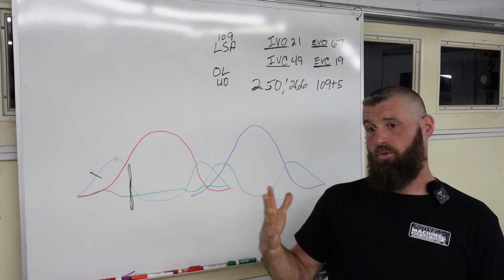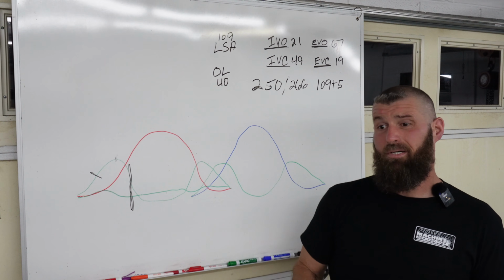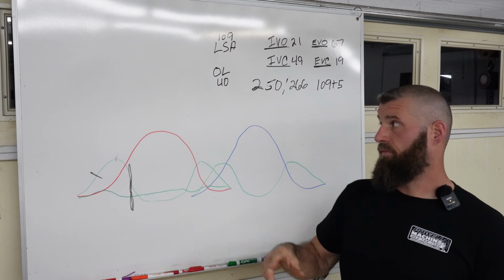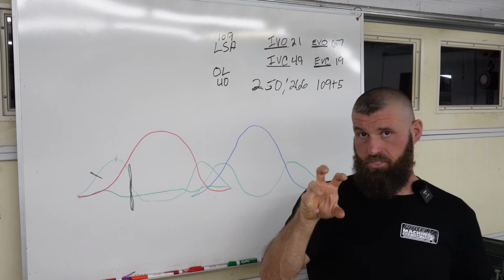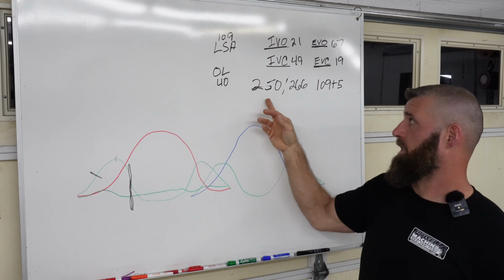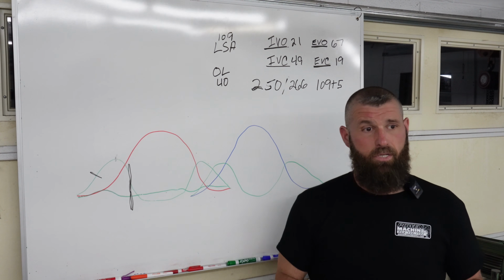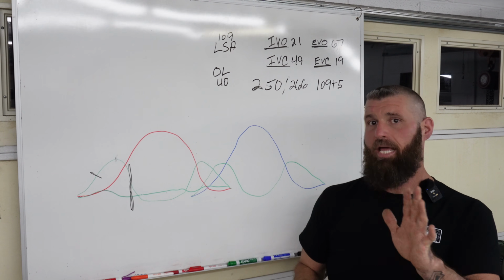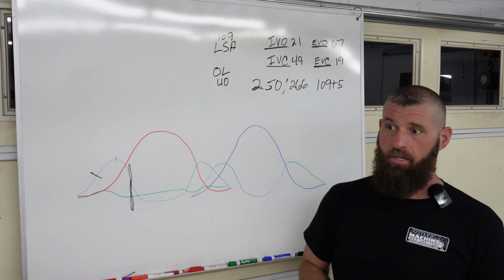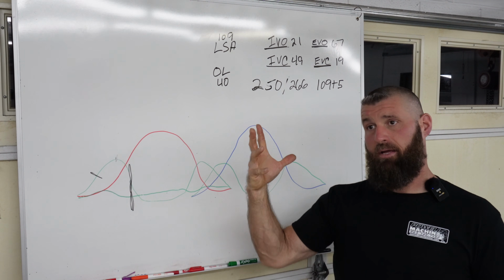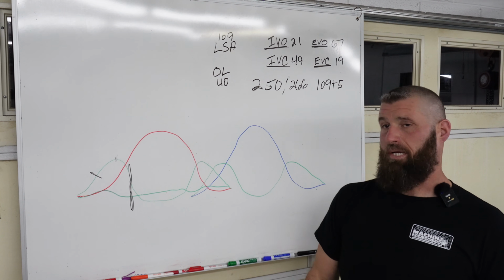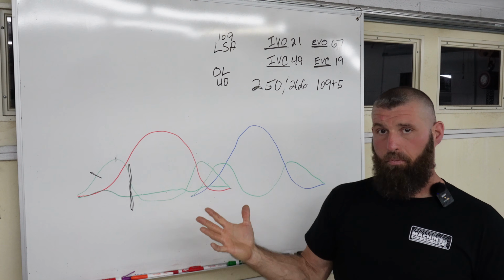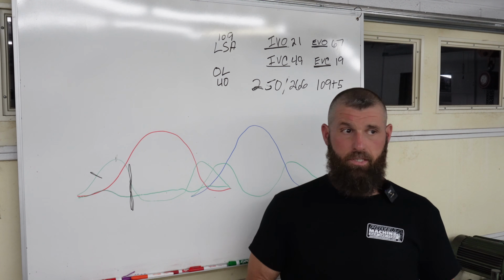And it depends on the package, but pretty much everything we do now, the split, because this was a specific question, the split between the intake and exhaust, I almost don't do anything less than 6 degrees of split. And we've got some Comp Eliminator and Super Pro type big block stuff.